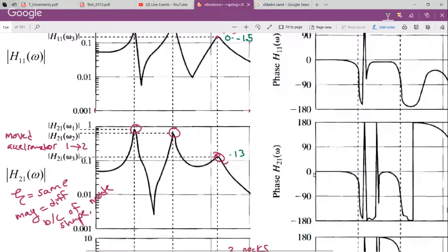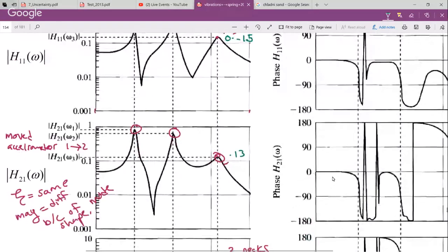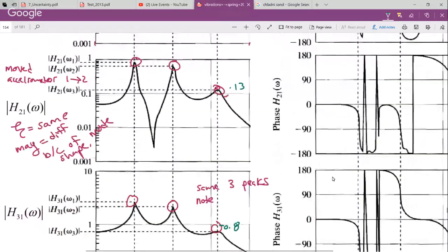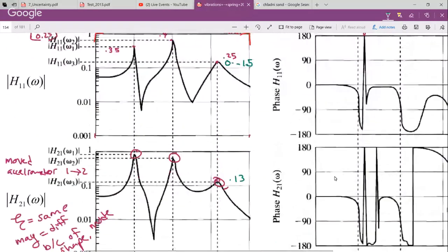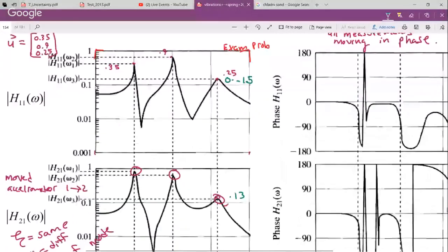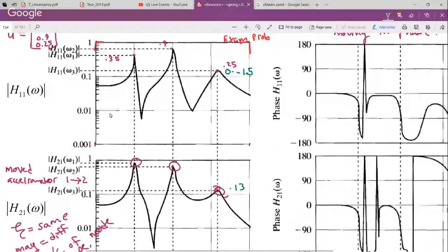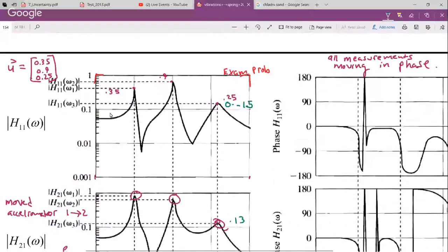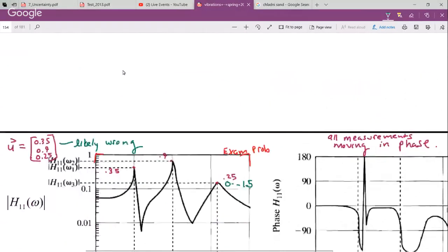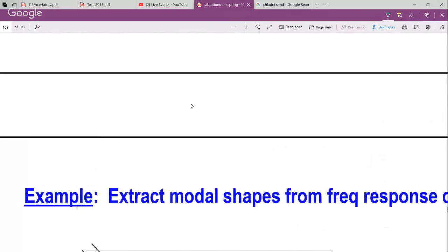We can formalize this whole approach, and that's what we've done here. If we take your multi-degree-of-freedom mass-spring-damper system model, go beyond that 8-step modal analysis, rewrite those in terms of both modal masses and frequencies and damping ratios, and determine the frequency response of those, which is basically writing it in the frequency domain, it's a little bit involved.